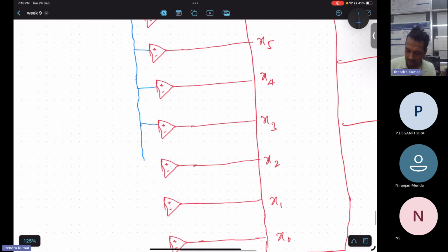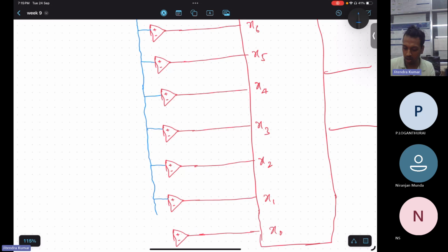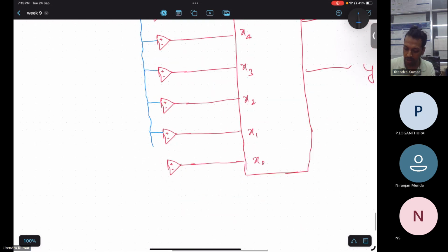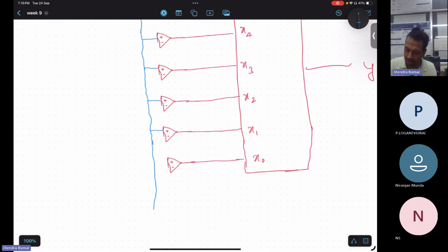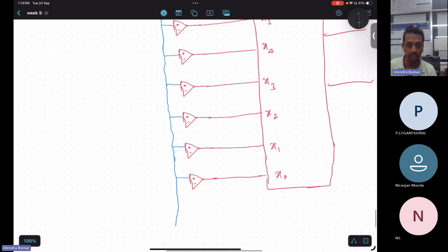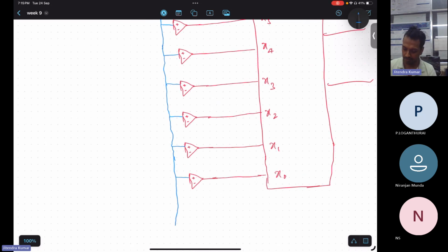And what will happen to the negative voltage? So that comparator will provide you a high value for what? In the last-to-last lecture we discussed the concept of comparator. So the inverting terminal should have a higher value than the non-inverting, then only it will provide you the higher value, isn't it?